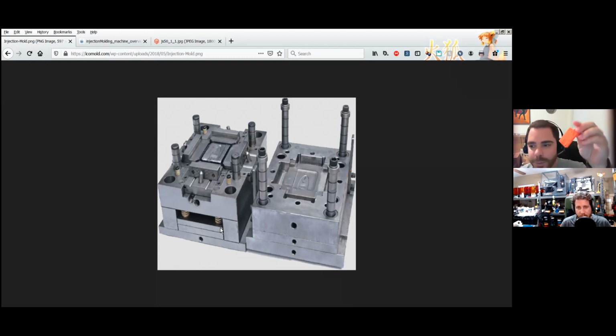So I don't know if this will show, if you could see that, but you've got, oh yeah, there we go. You can see the little round spots where the ejector pins were, they're a little bit shinier than the rest of it. Exactly. Is that because these pins are warmed and so they're actually melting a little bit of the plastic as they're pushing it? That's possible, but it's probably not by design. You know, this is the backside of the part. They don't care so much. I mean, that part's literally designed to be thrown away.